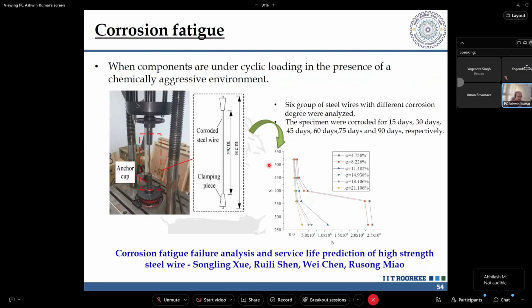Now the important discussion to think about here is that whatever structure we are designing, whatever bridge girder we design, is for the pristine condition of steel, and also assumes that some kind of maintenance will be done over the steel girder. What if corrosion happens? People have taken steel fiber, steel rods, and steel plates, and they have done aggressive, or accelerated, corrosion tests, like the immersion test specified in ASTM, whether a salt spray chamber test or similar. And they have developed the SN curve for that particular kind of thing.